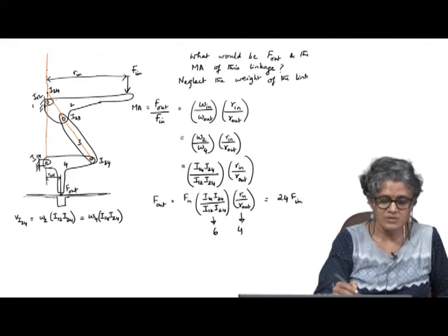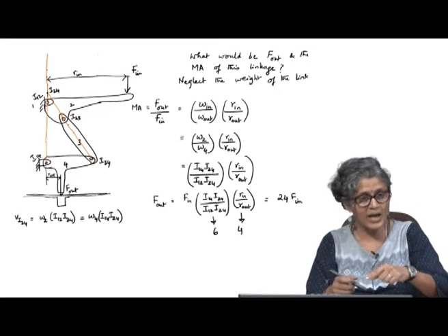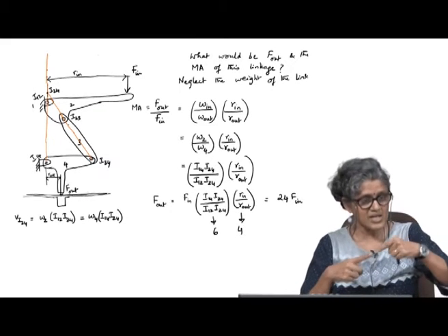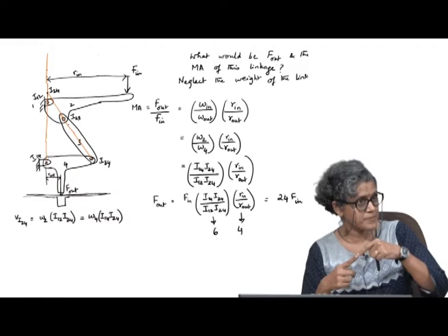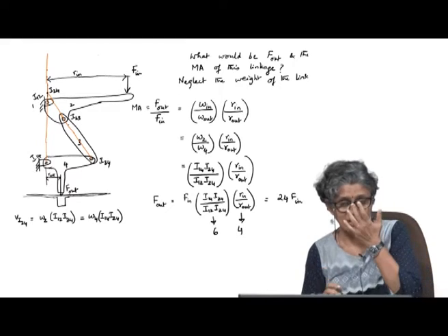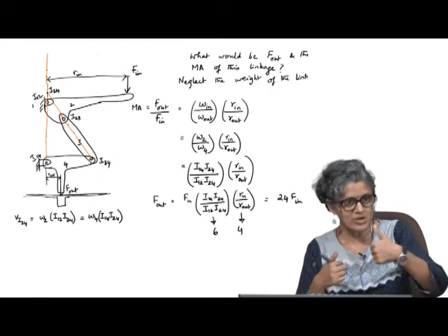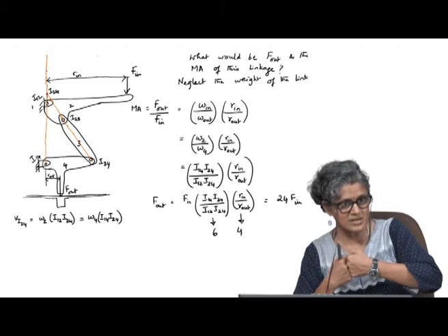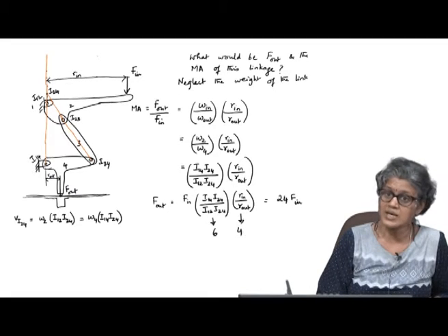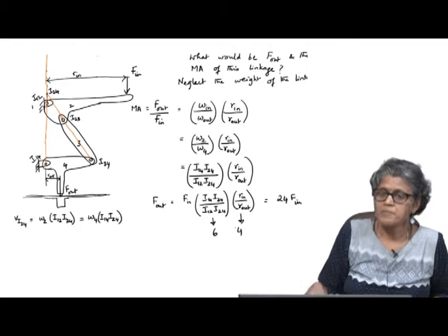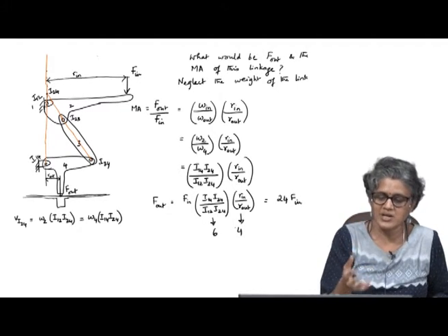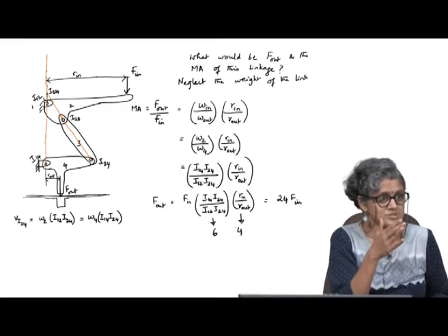So as you are nearing the toggle position, where these two links are in line, I24 and I12 will actually coincide, which makes the mechanical advantage infinite. But obviously the parts have to be able to withstand the forces. Close to the toggle position, you can get a really high mechanical advantage. So most punch presses, or anything where you want to generate high force, will operate close to the toggle position.